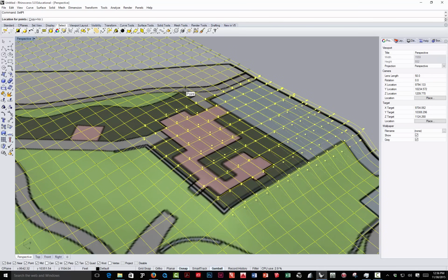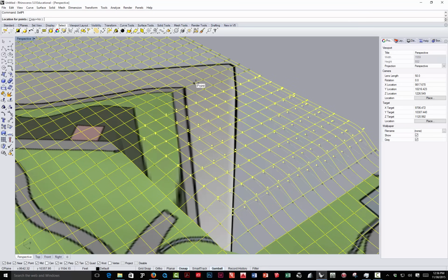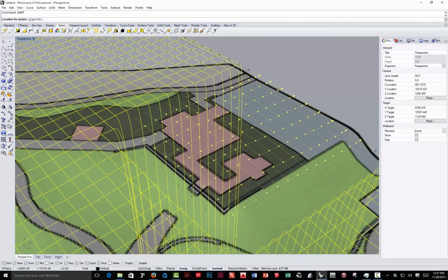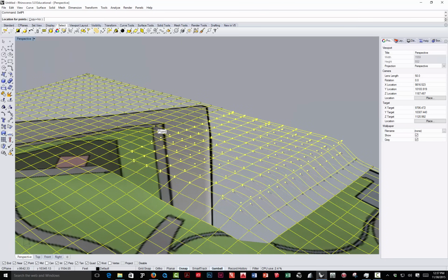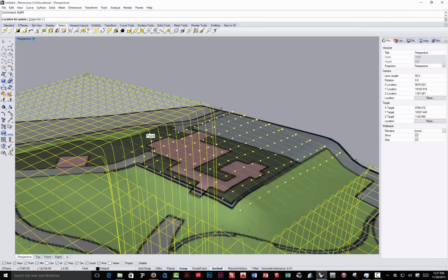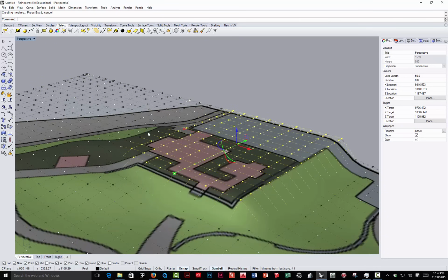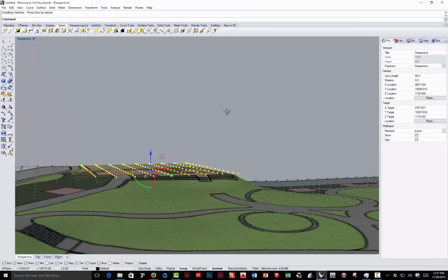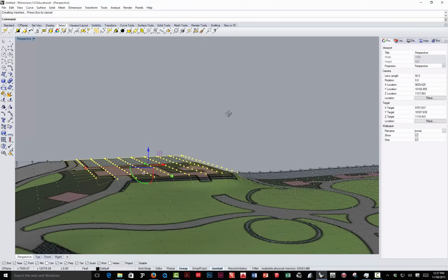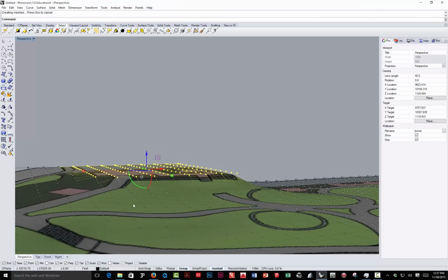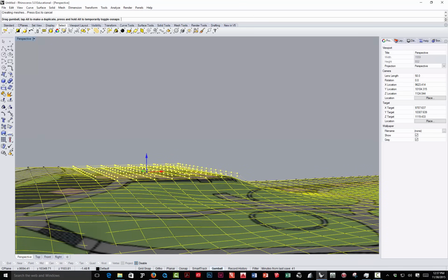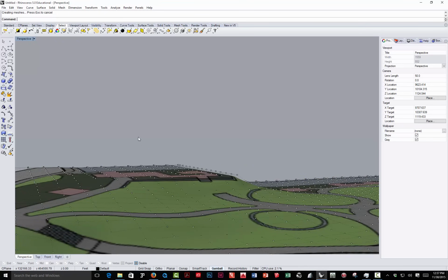What I'm going to do is move over here, out to the edge of the road, because that's the point where we want this to snap up to. So I'm just moving over till I get the surface lined up, maybe right in there. Click. And now you can see it's set that up. Now that might be a little too high because I can see this walkway is really sloping up. If that's the case, I can now disable that. Now that I have them set, I can pull that down a little bit more. Yeah, that looks pretty good.